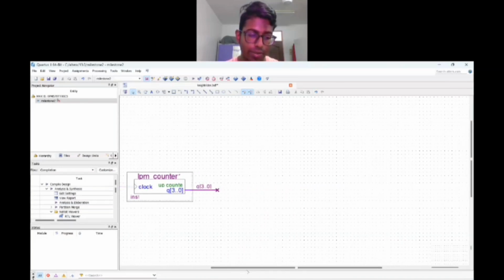A BCD decoder usually has inputs, and there will be multiple outputs. Basically, it decodes the input into output. The decoder we are going to use is a 7442 BCD decoder, which has 10 outputs and accepts a value in the range of 0 to 9. The output is active low, and a value greater than 9 causes all outputs to be high.